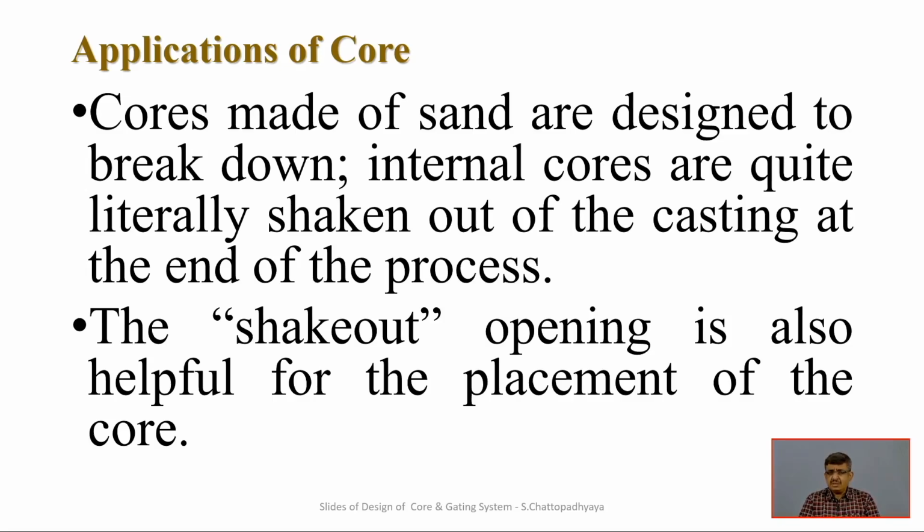These cores are definitely made of sand, but with some other features that are designed to break down. So collapsibility is a very important role to play. For the molds also collapsibility is important, but for the core the collapsibility is more important, because it has to be appropriately collapsed, since those outlets may not be as big as they are for the mold. So collapsibility has to be ensured so that it can be easily broken down after the casting.